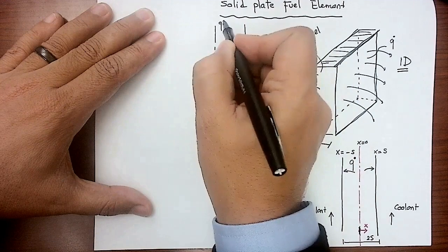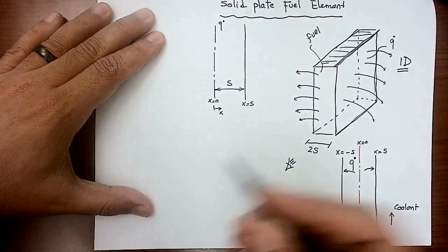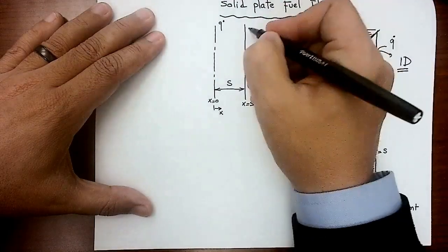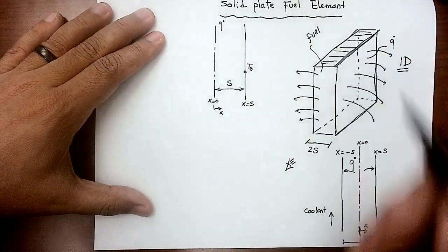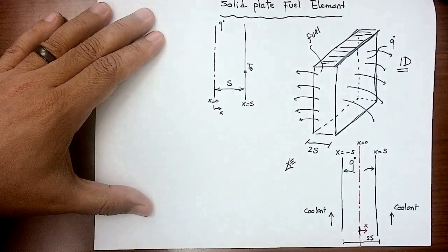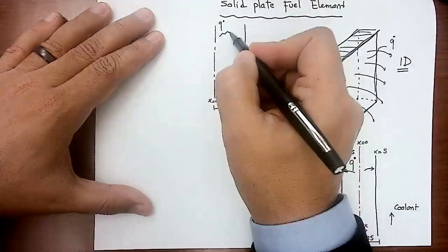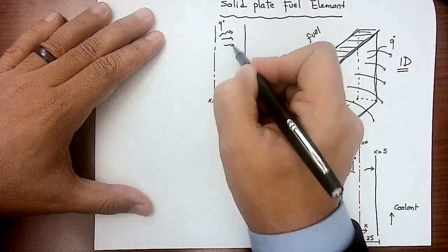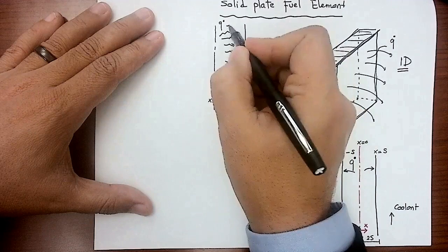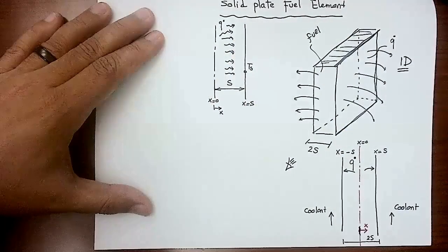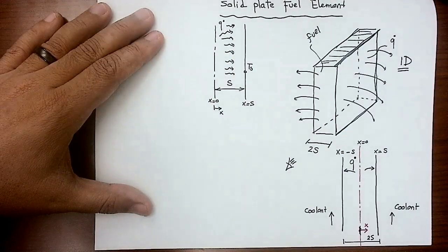There is heat generation in this body, right? Let's recall that the surface here, the temperature is Ts, the surface temperature. Then, because there is internal heat generation, heat is going in that direction by conduction inside the fuel, right? Whatever that Q is, I'm not interested in how much is inside the fuel.